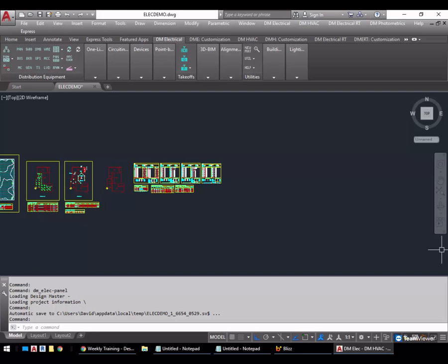But because there's so many different pieces in the NEC, you have to know what you're doing in order to get everything set up right. There are all the different options in the NEC, so you want to make sure that where you're putting your loads corresponds to the appropriate setting in the section in the NEC so that all the calculations end up working out right. So we're basically looking at the dwelling unit portions of NEC 220.42 through 220.85, both the main dwelling unit calculations and then the optional calculations in 220.82, 220.83, 220.84.